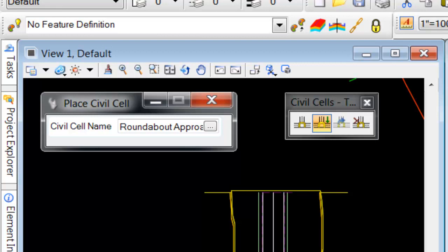When you use corridor tools, like these corridors out here, it automatically assigns profiles to the lines that are part of that. So you don't have to go out and try to put an edge of pavement profile in there. It already comes across with the template that you place on it. So that's one good thing about it. It's already there. Pretty smooth. Okay, so pick that just inside circle, just inside the outer circle. Click that one. And then the third one is the outer circle. So we can go all the way out to the outside edge and pick that one.